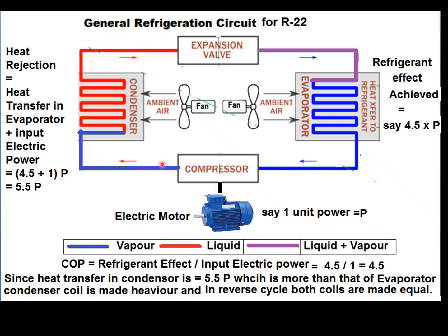Its temperature is enormous, so it is sent to the condenser for condensing the refrigerant and bring its temperature back, to the expansion valve where we reduce the pressure. So whatever pressure is increased by the compressor up to this part of the circuit is reduced by the expansion valve in this part of the circuit.